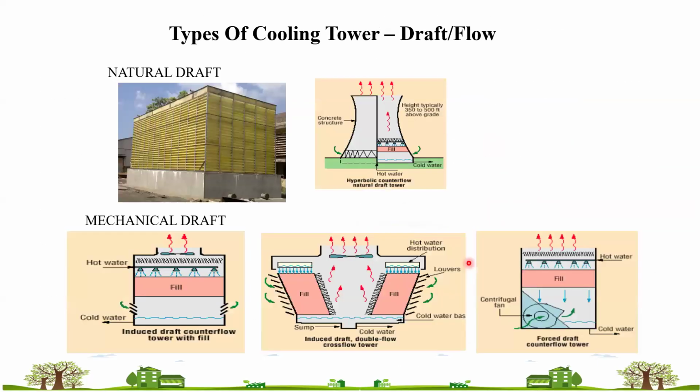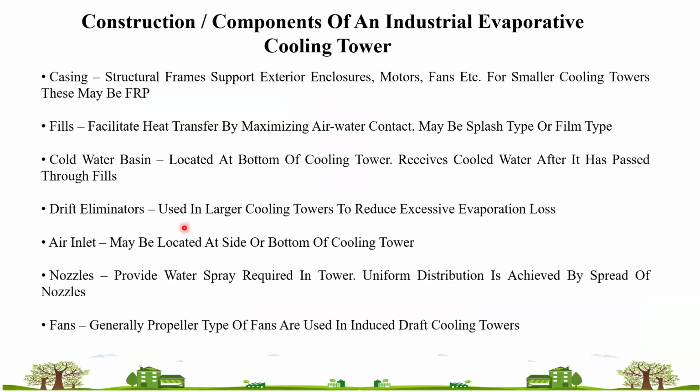So this is your cooling tower, and you can measure air velocity at this exhaust point. Then you can measure the power of that particular fan. Then the temperatures of the inlet water here, and you can measure the ambient air temperature here, and then the exhaust air temperature here. So all these equipments are used to evaluate the cooling tower.